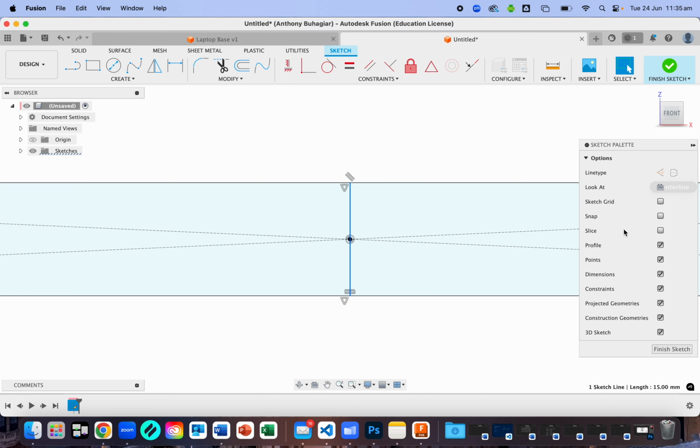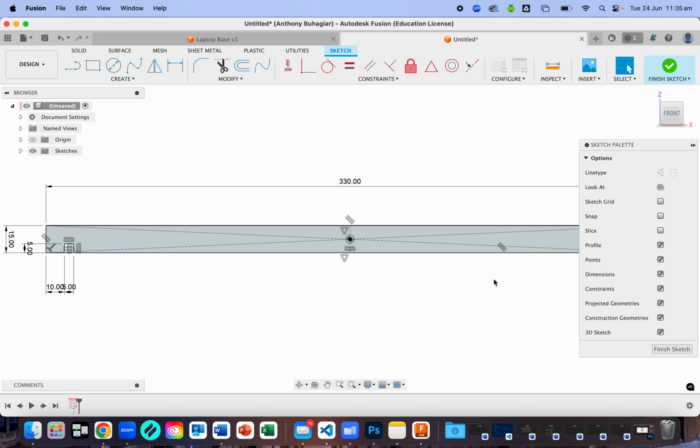and you can see when I select the line, I'm coming over to the right hand side and I'm changing the nature from a drawn line, and if you look at what my cursor is going to do in a second, it's going to select something that we call a construction line feature, what I've just done there. Okay, now a construction line isn't a line that we can use to draw on, but I'm going to show you a new function here.